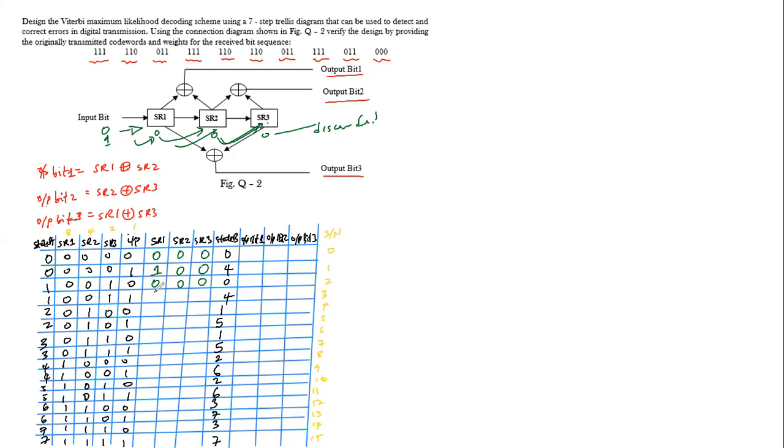The same thing applies here. So when we feed in S1 with the input 1, what was held originally by shift register 1 is 0, so that moves to shift register 2. And what was held in shift register 2 was 0, it moves to shift register 3. Now, 1 was held originally by shift register 3, that is equally discarded, right? Then the same thing applies here. We feed this input to the 0, so that moves, then that moves. So we feed this with a 1,